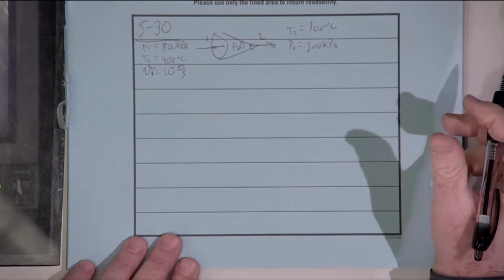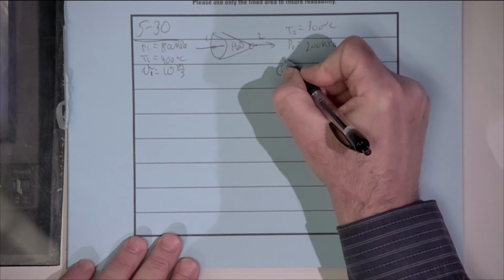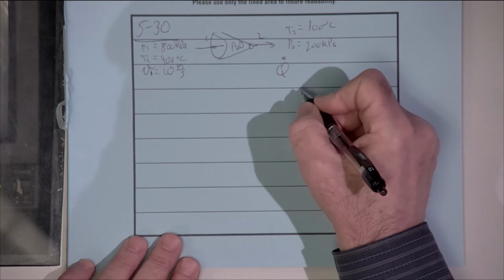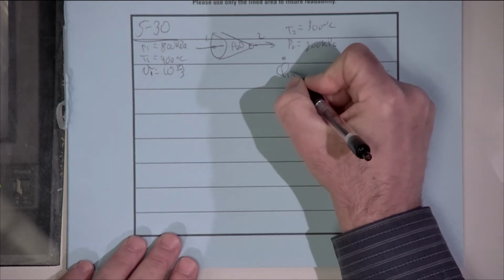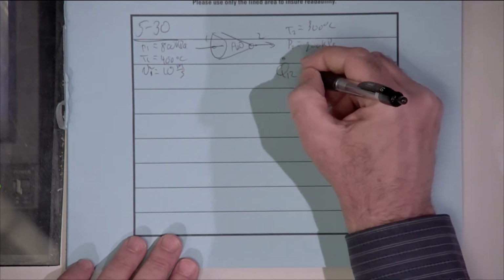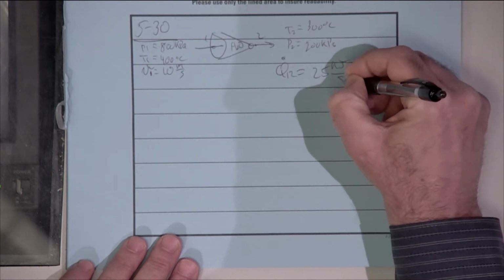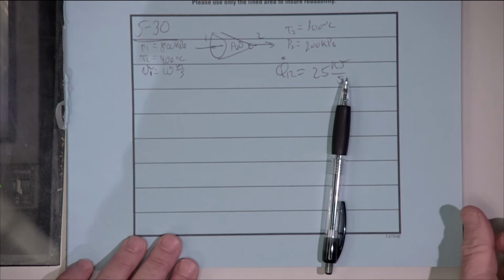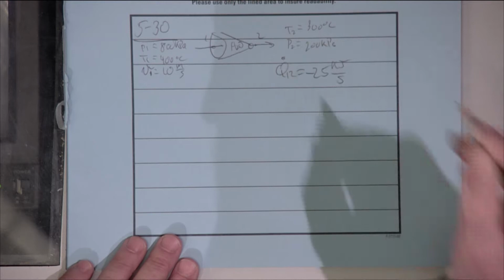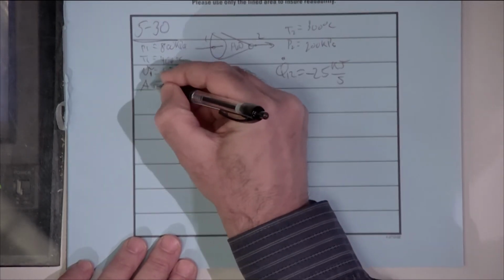And then it tells us that we're losing heat at the rate of 25 kilowatts. So that's a rate of heat transfer. So I'll put Q dot. I'm not going to put the subscript CV for control volume. I'm just going to put the subscript that represents the inlet and the exit condition. So I'm just going to put a Q dot 1, 2. And in magnitude, this is 25 kilowatts, which is the same as a kilojoule per second, which is how I prefer to use the units for heat transfer rates. But this is a negative sign, right? To be consistent with our sign convention, we're losing heat from the system, so we have to show this as minus 25.